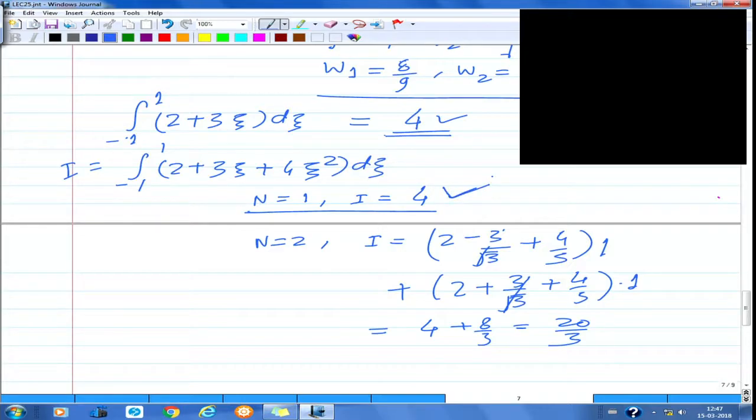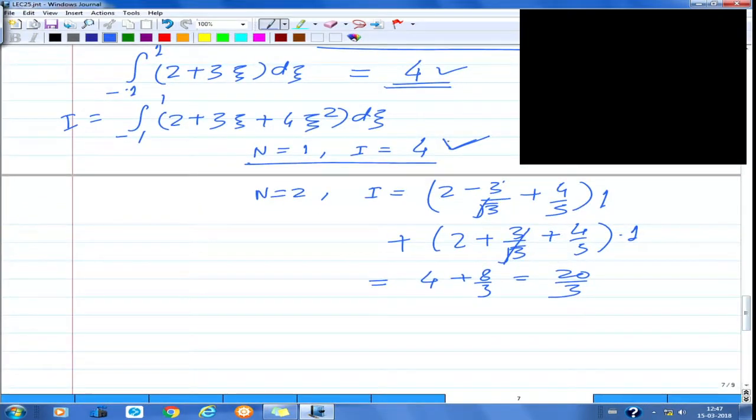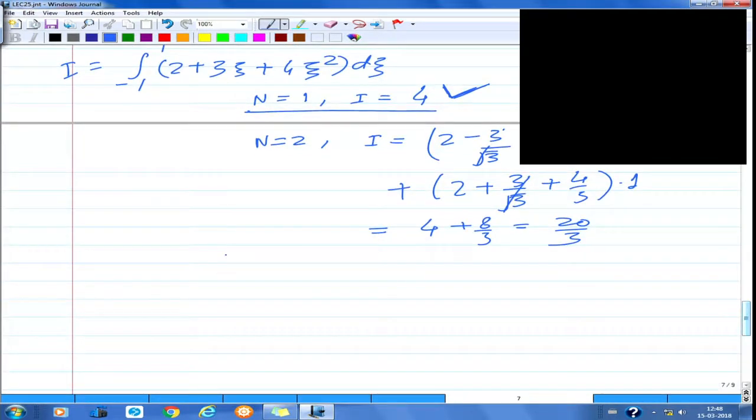So that is what we use for eliminating the shear locking: reduced integration. So we evaluate it on the lower side compared to its exact value. And now let us say the same thing, I want you to appreciate that. Let us say if you use n equal to 3, then what happens? Please do that and tell me what you get if you use n equal to 3.